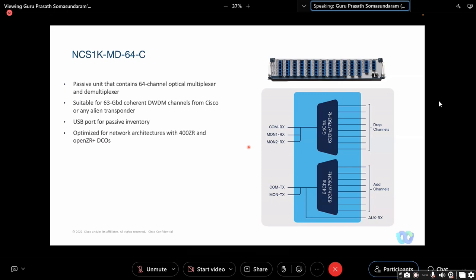So the MON, there are three MON ports, right? For both the 64 gigabits. That's right. So will all three be connected to the EDFA? No, only one and two. The Mon 1 and Mon 2 RX will be connected to the EDFA, and the TX would be for external use, if you want to use it.